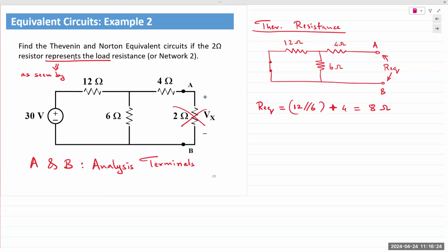Okay, how about Thevenin voltage? The circuit to determine Thevenin voltage is completely separate from the one that we used to find Thevenin resistance. Remember, 3 quantities, 3 independent analyses, 3 completely different and distinct circuit diagrams. The circuit that we used to find Thevenin resistance has no bearing whatsoever on the other 2 analyses: Thevenin voltage, different circuit; Norton current, different circuit. So now draw out the circuit that you think would be required to analyze for Thevenin voltage.